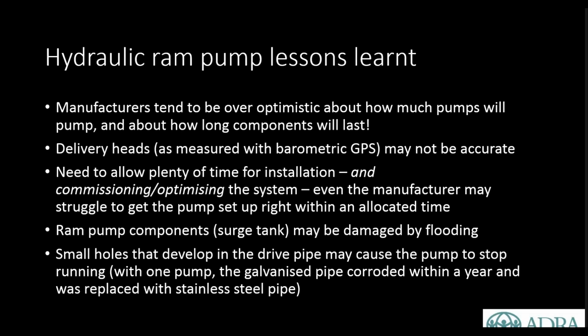So we had to replace that pipe with stainless steel pipe, which of course is a lot more expensive than galvanised pipe. When you consider that you've got a long length of pipe, maybe 100 millimetres in diameter, that can add a significant cost to the overall system.